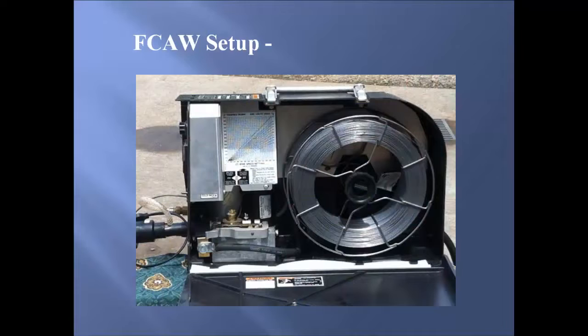Here's a view of the flux core arc welding machine showing the inner workings. By unclamping the door, it will reveal the wheel of electrode on the right side. Then notice the power source cable connected to the bottom left side. This is important when testing with the amp volt meter. Then on the outside left of the box is the welding lead connection.